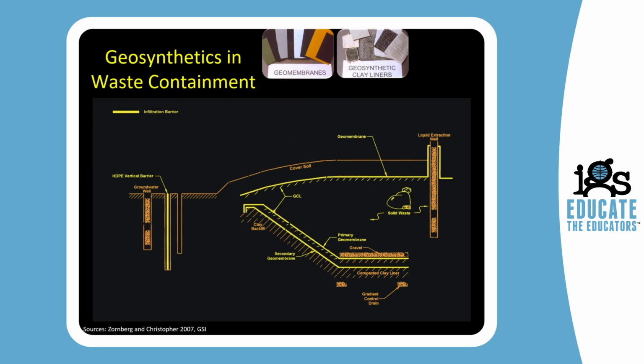In addition to these yellow infiltration barriers, we may need to stabilize many of the components in a waste containment facility, and that's when we have these green reinforcement layers. In the cover system, we have geosynthetic reinforcement on top of the geomembrane. This geogrid on top of the cover system is to provide stability against potential sliding.